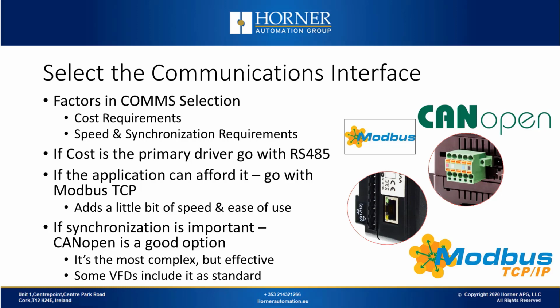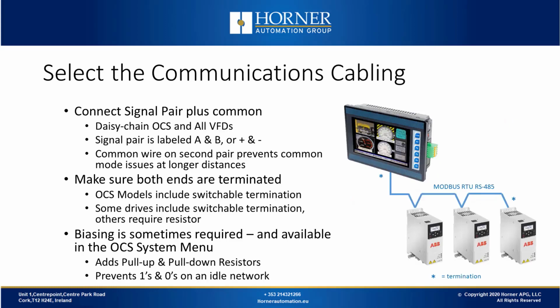You might have multiple motors that need some level of synchronization. If that's the scenario, then CANopen is a good choice. CANopen is a very popular fieldbus network and a lot of drive manufacturers support CANopen. It may be complex, but it is effective.